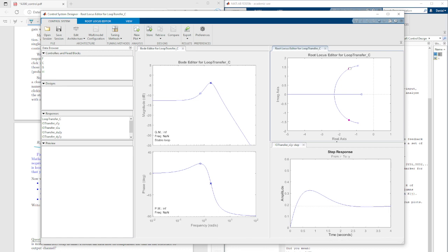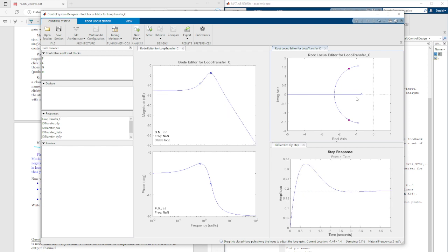So 0.7, come on. Okay, let's go with 0.71. So it's roughly okay. So Matlab adapted our step response. Okay, we still have quite some overshoot, although we have a damping of 0.7, but that is due to this 0 we have in the numerator. But we know that the damping is actually fine, the eigendynamics are well damped. Okay, we know we can do something smarter to work with the 0, like a feed-forward controller,